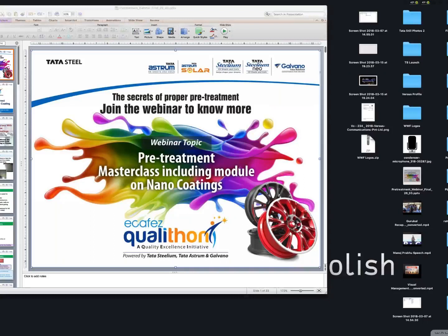Now there are some questions I'll just go ahead with. Mr. Shaktivelan S. asks: which element in RP oil can't be removed by degreasing chemicals? Now if you have good degreasing chemicals, basically most of these oils will get removed. In rust preventive oils also, they are majorly hydrocarbon oils and they can be removed easily with good degreasing chemicals.